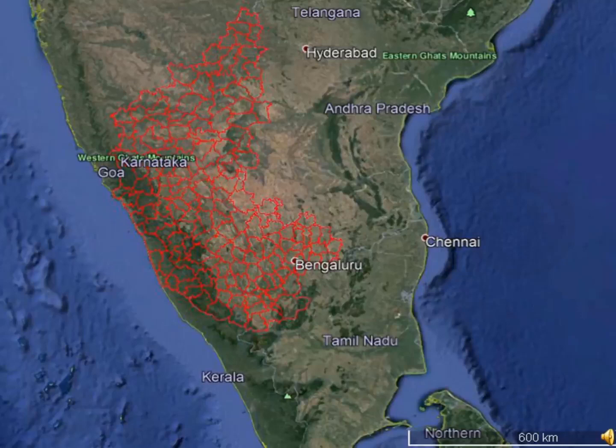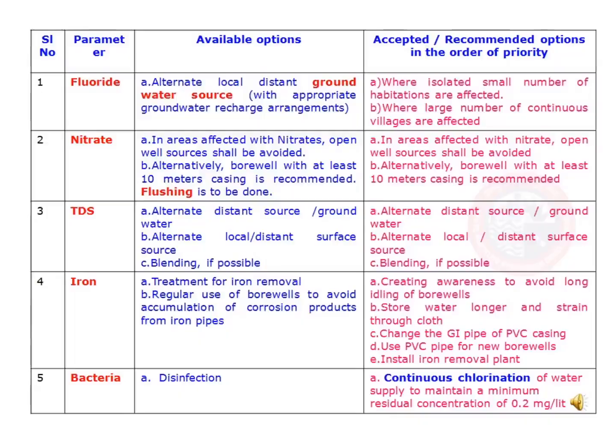This vector GIS map is also overlaid on Google Earth. The analysis of water parameters is correlated and interpreted, and the reasons for degradation of water quality were arrived at. For the improvement of borewell water quality, suggestions were derived through analysis. By this, GIS technology helped with data capturing, interpretation, analysis, remedial measures, and conclusions for improvement of water quality to a larger extent.